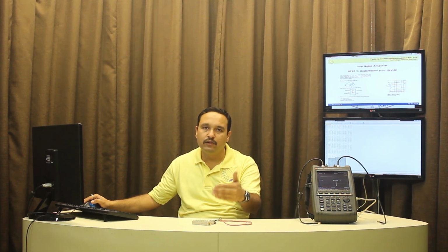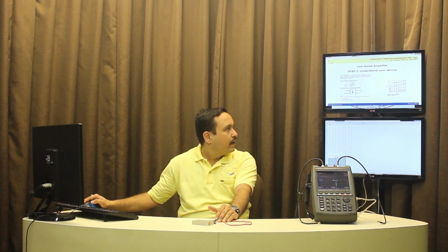So the next step is to look at the S parameters that you have received from your manufacturer, or if you are using an EDA tool, you could simply simulate your transistor model for the S parameters for a particular bias. In this case, I will simply read the S2P file, the data which you have received from the manufacturer, which I have shown before, and I will simply plot those.